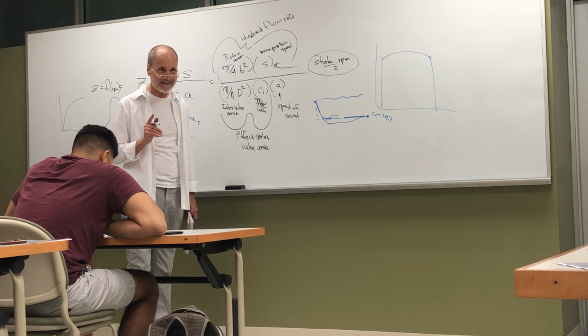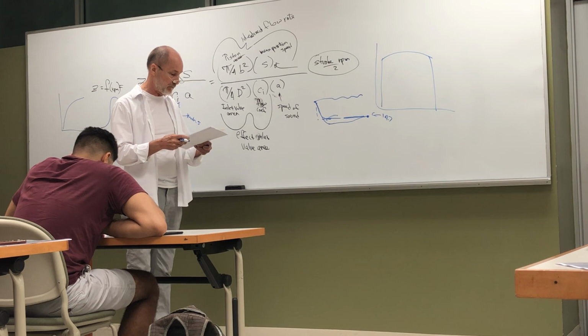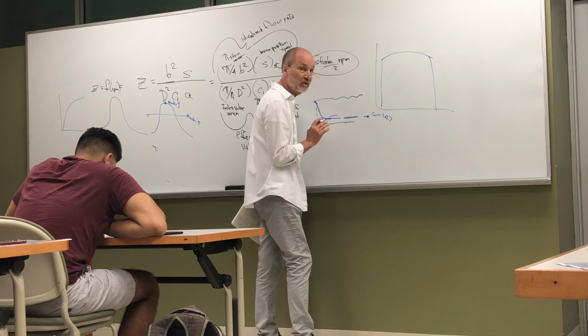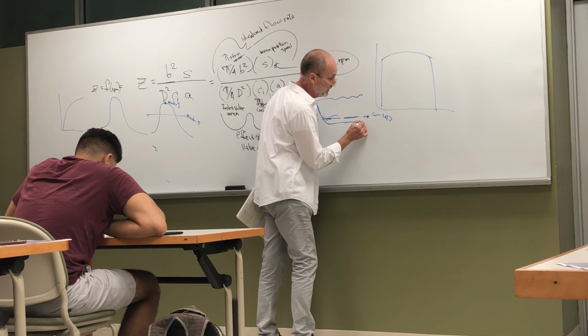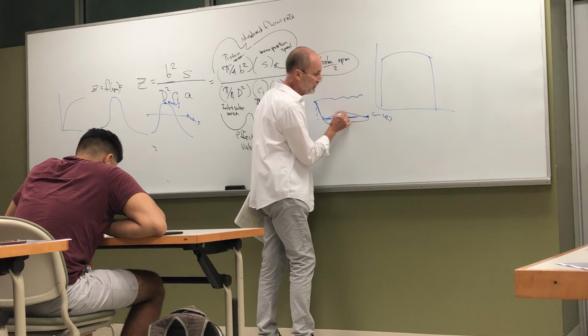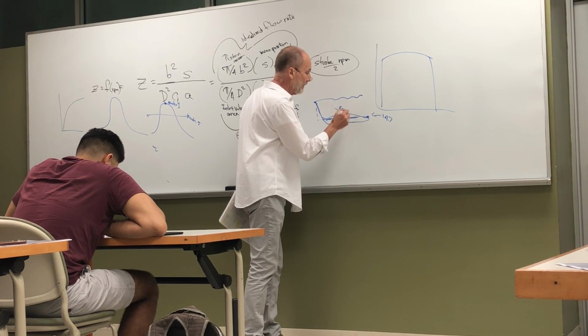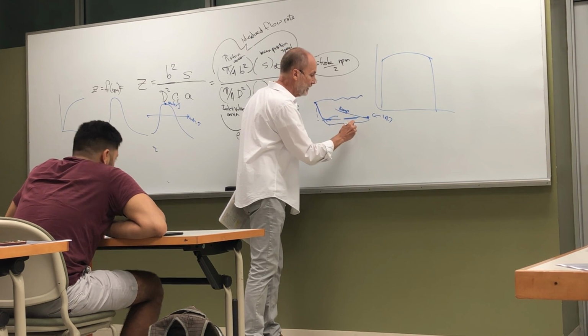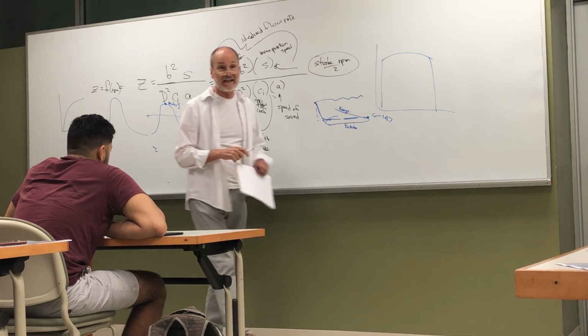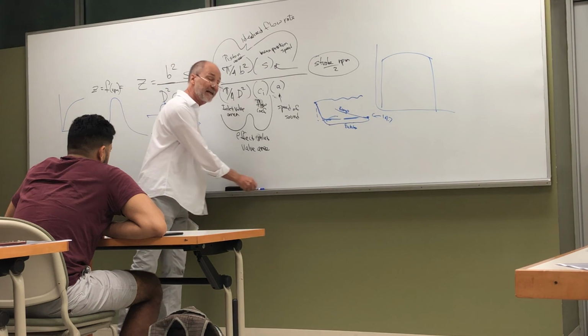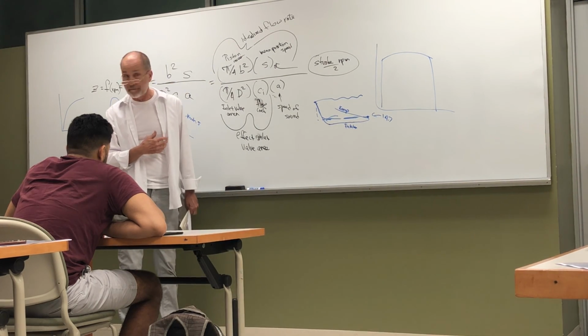so we really haven't experienced a drop in volumetric efficiency yet. At Mach index 0.6, you'll see we have so little time, the gases are rushing into the cylinder, they never get back to atmospheric pressure before the compression starts. Here's compression, here's intake. Now we have less gas in the cylinder. We're beginning to see a drop in torque because we can't get enough fuel and air into the cylinder.